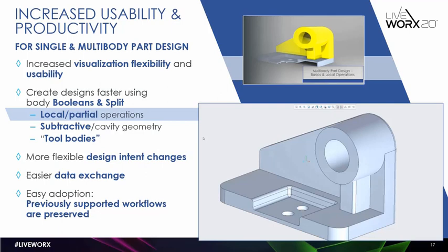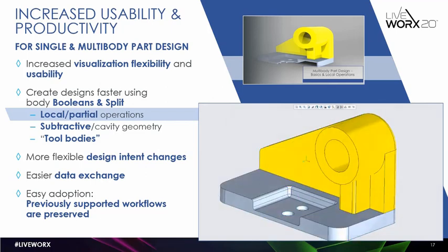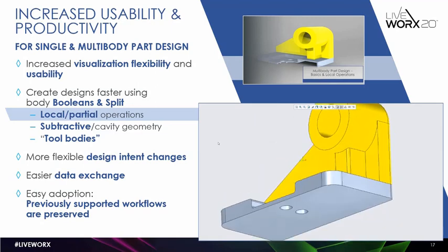The demo shows a situation where we want to only shell the lower portion of this part. We can now either design the lower and vertical geometric features as two bodies, or simply split the body into two as shown here. We apply a yellow appearance to the new body to better distinguish it, and can then invoke the shell command that previously shelled the entire part geometry to easily now only shell the gray body. This localized the shell operation as required.